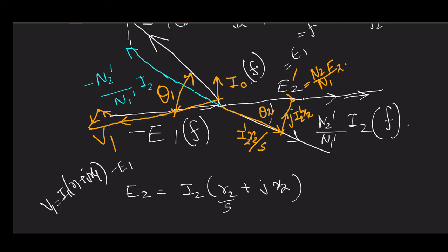If we put an electrical load across our transformer secondary, how does the primary side sense that a load change has taken place in the secondary side? That analysis we know: the secondary side change in current produces a change in demagnetizing MMF, and by sensing it, the transformer primary side also changes the input current to counterbalance that change in demagnetizing MMF produced by the secondary side current.